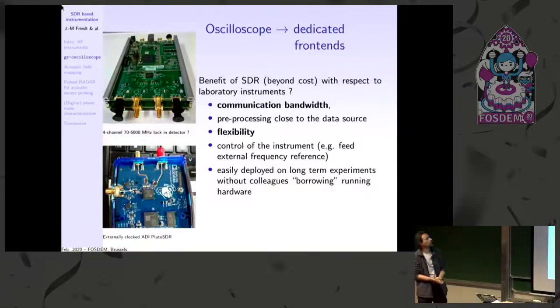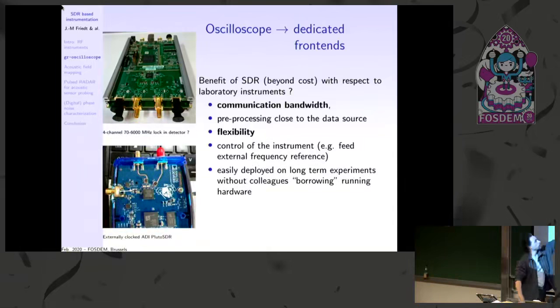And then I thought, okay, let's try to show a little bit what we're doing with other front ends. Doesn't this look to you like a coherent 4-channel lock-in detector? I take 2 B210s, I take the 1 PPS to lock their inputs, and as long as I keep continuously streaming the data so as not to lose phase coherence, I have a 4-channel lock-in detector, but with the added advantage that I don't have to go for VXI or GPIB to collect data.